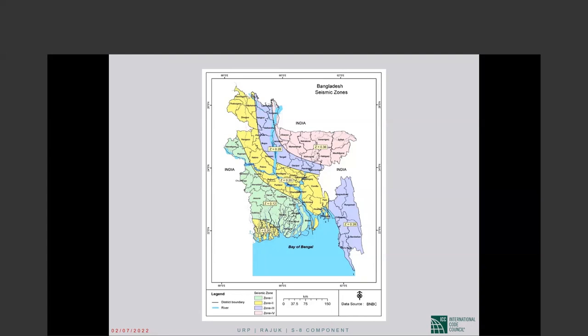The repair itself is expensive and it is disruptive. So the building will probably not be possible to occupy while the repair is going on. An existing building with a weak story is a significant problem, and there is no one answer that anyone can give you. It will depend on the building, what you can do, or what would be a more effective solution.